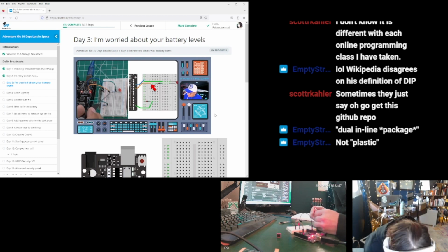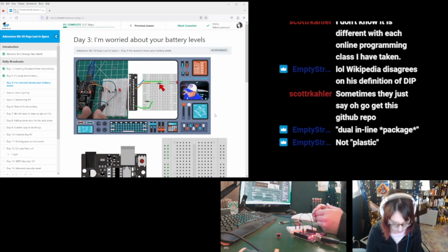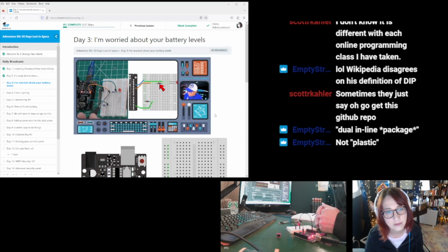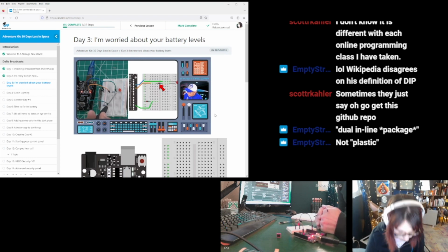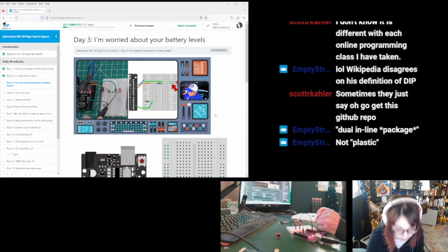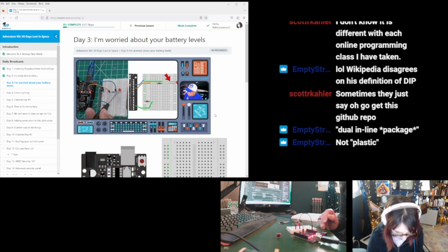From that connection on pin 12, we pass through a current limiting resistor. And you'll remember from our discussion last time that we've chosen the value of this resistor to give an appropriate amount of current to light our LED light bulb. The current after passing through this resistor passes into the positive terminal of the LED lamp, and we've positioned it so that the current will come out of the lamp on row 11, just above there. Now, in order to complete the circuit, we're going to have to provide a return path back to ground.